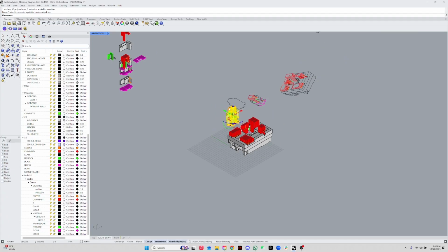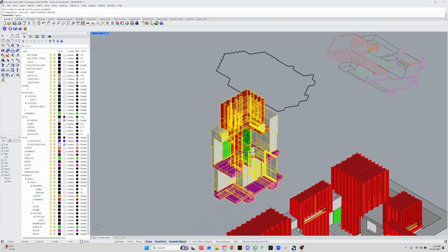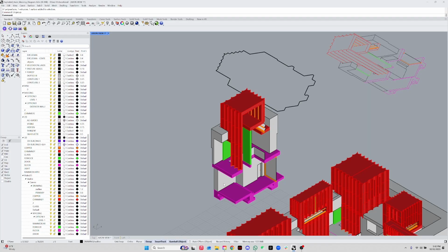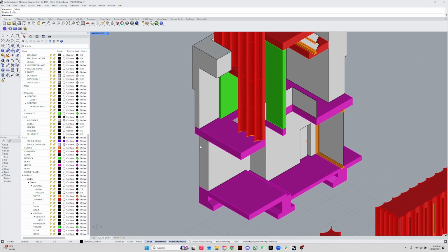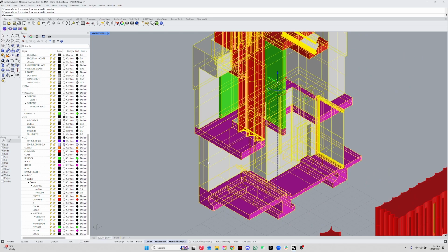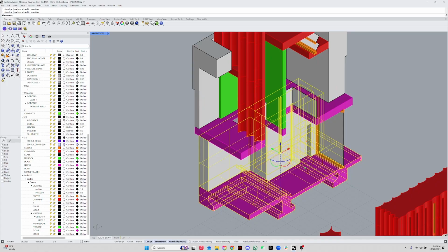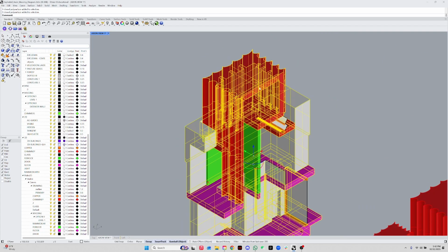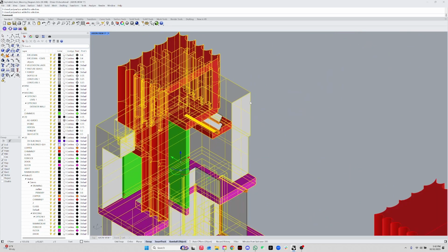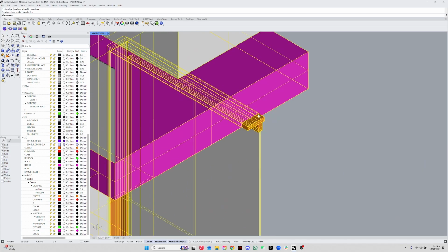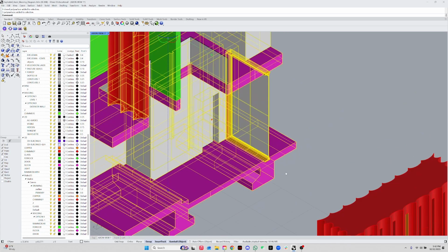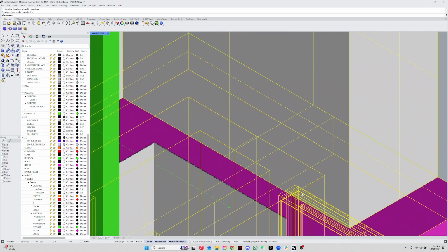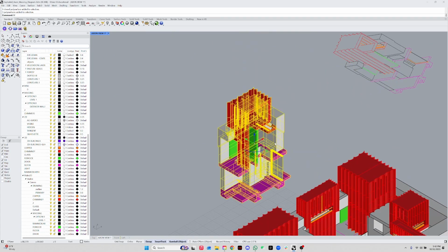Sometimes it depends on the model itself. So sometimes I'll just take it out. I'm gonna ungroup it. And then this is something I like to do. If you have a heavy model, you don't want to select everything. You can just select the outer stuff of your model, so then it's not really picking up everything. So now that I make sure that I selected everything in my outer layer, so I'm not picking the interior stuff of this model, I can just do mesh outline.